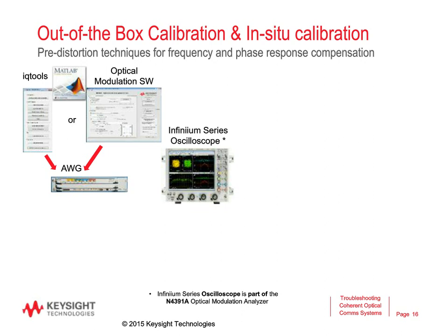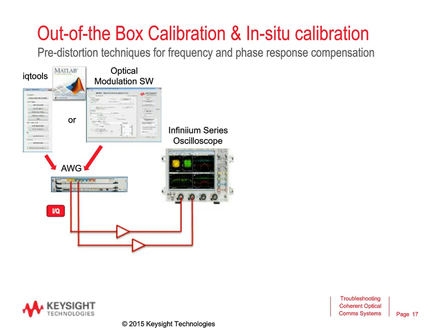And the calibration works like this. We download a signal into the arbitrary waveform generator. Then we hook up our amplifiers that we are probably going to use to stimulate our modulator. So in this case, I'm trying to get the frequency response out of the signal path and also the cable distortion or cable losses out of the signal path by connecting the output directly to the oscilloscope.